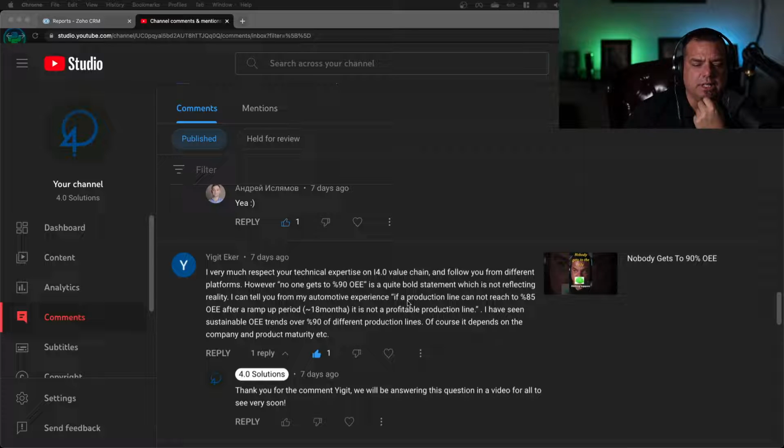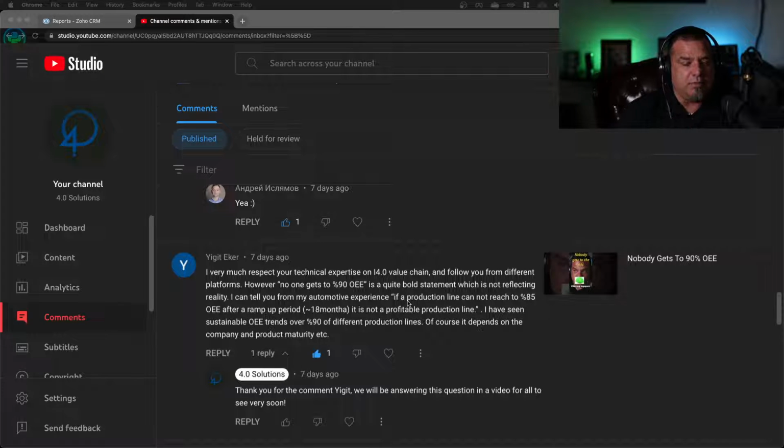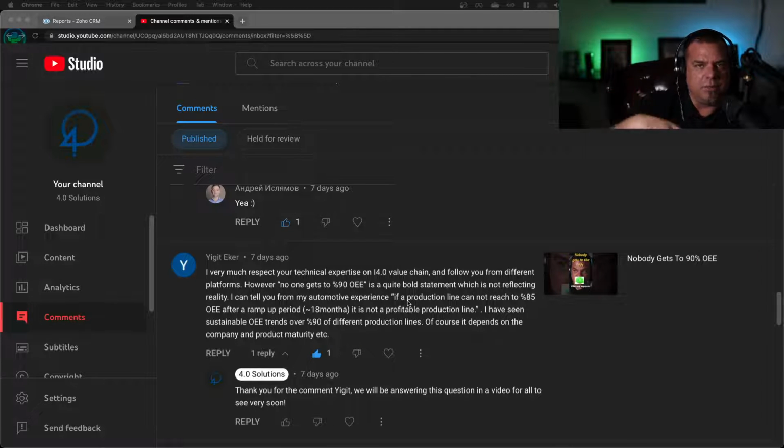The answer is no, you haven't. What you have seen is a number that has been manipulated through various techniques. The most common techniques in the automotive industry to manipulate the OEE number, there's really two of them. Number one, they'll only use two of the three underlying values to calculate OEE. This is very common in Japanese companies, where they'll only take performance and quality, multiply those two together, and say whatever that number is, that's the OEE number. And this is very common. We've seen it in dozens and dozens of examples of Japanese car manufacturers and their suppliers, okay? That's number one, the manipulation of the calculation to get the outcome that we want.